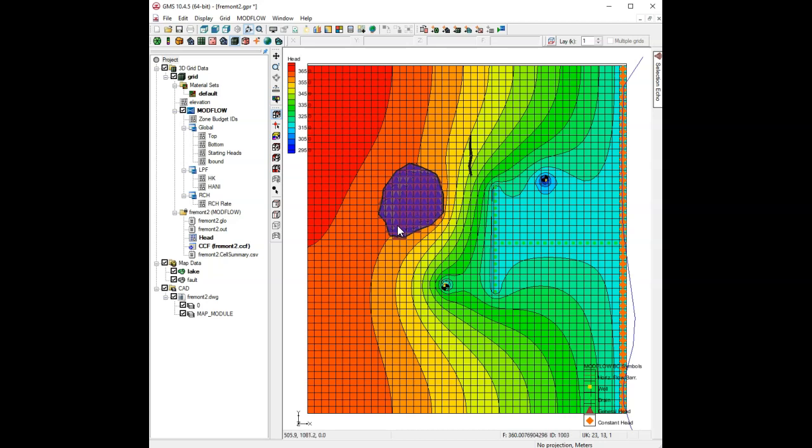It's primarily a source, but I would guess maybe over here on the uphill side, because now if you look at the left side, you'd go just outside this boundary, and the water table is just above 360. And so over here on this side, we're probably getting some cells where water is leaving the aquifer into the lake, but for most of it, water's going from the lake into the aquifer. And so that's kind of an interesting application of the general head boundary condition.